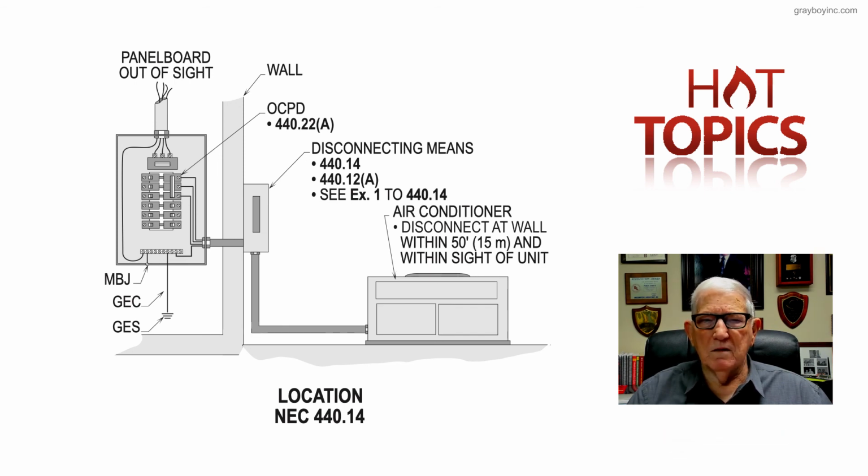But we've gone over the definitions with you. We've shown you this disconnecting means in the illustration. And if you notice, some people say, well, that's an outlet. They'll go to the unit, and remember we reviewed an enclosure that enclosed the controller and so forth. But notice the conductors are routed through the disconnecting means and then to the AC unit, and then they are terminated.